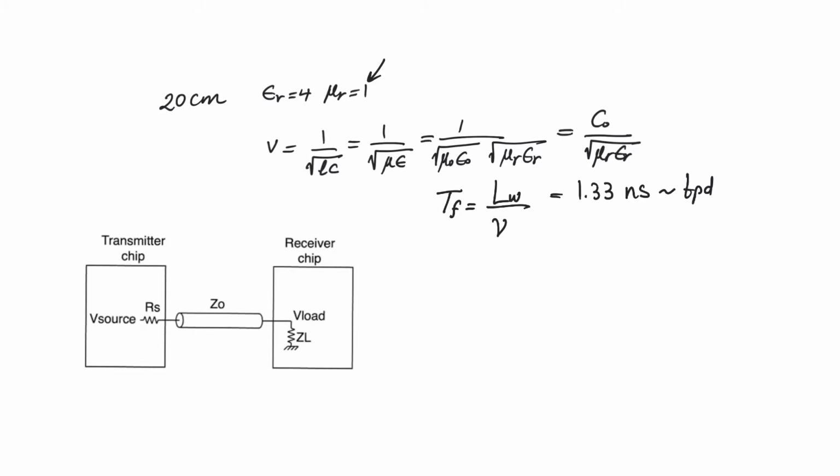So a transmission line is characterized by something called the characteristic impedance, Z0, and the characteristic impedance is a small value normally. We're talking about something in the order of 50 ohm. And it's important to understand what value this resistive impedance is, because depending on the values of resistance observed at the source, the transmitter, and at the receiver, the load, we can determine the reflection coefficients.